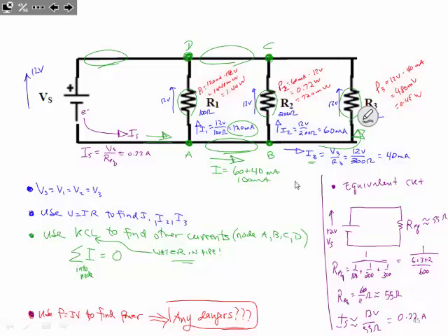If that's 100 milliamps, let's move backwards here. I had my source current that splits into 120 milliamps going up and 100 milliamps going over to feed our other two pieces of the circuit. So our total current must be what then? 120 went up through here, and then 100 went to the right. So our total must be 120 plus 100, so we should have 220 milliamps.